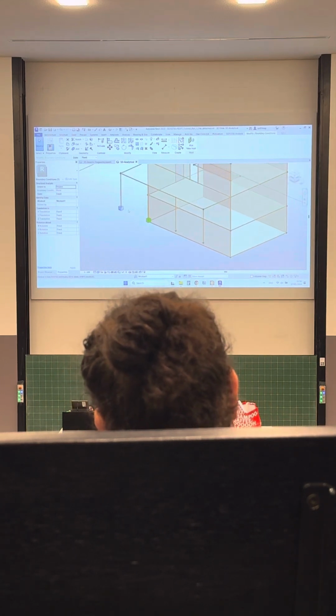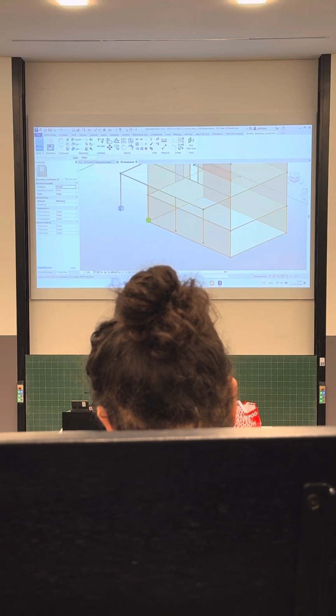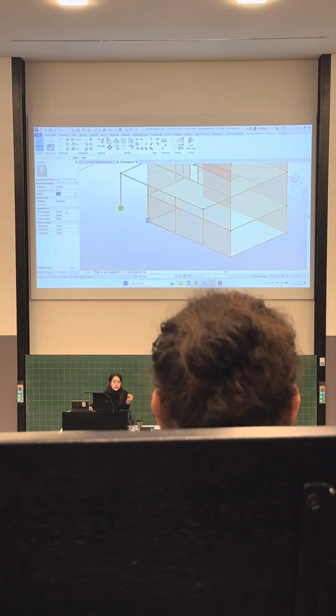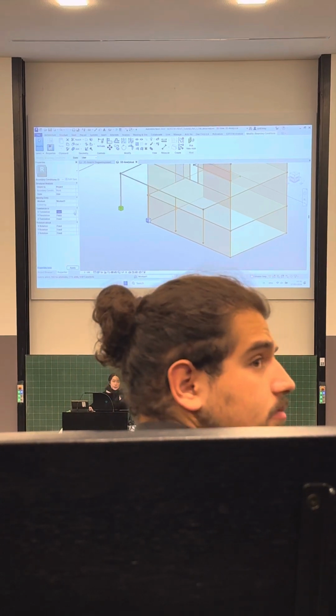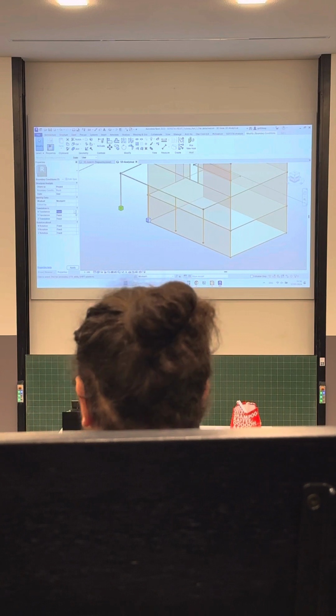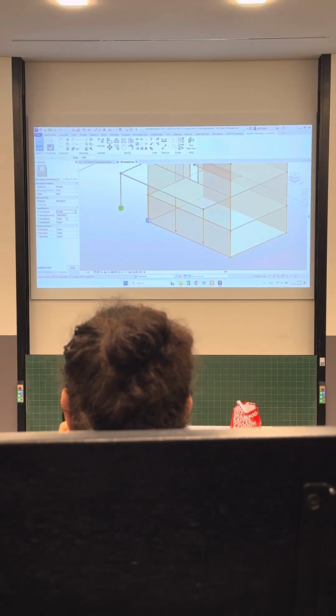Okay. Now in the properties, you can see the difference. This one has stayed fixed, because all the translation and rotation is fixed here. But if you go to the user here, you can actually give different values to your translation and rotation, to your degrees of freedom. For example, I want to have a spring, and you give the modulus. But for simplicity reasons, we're not going to have it today. We're just going to make them all fixed.